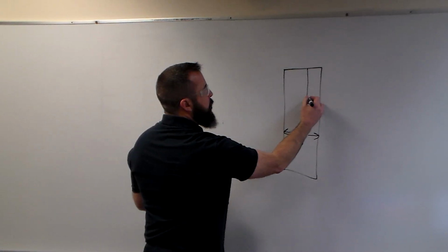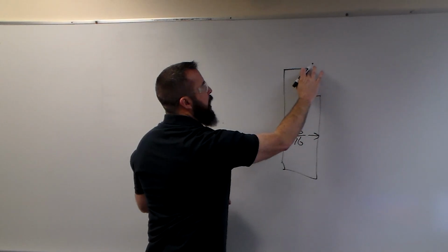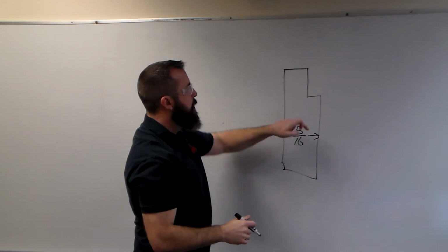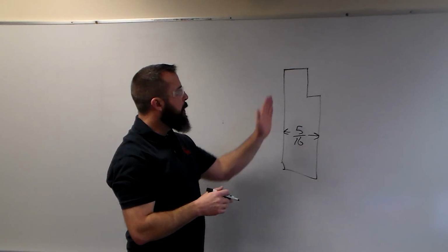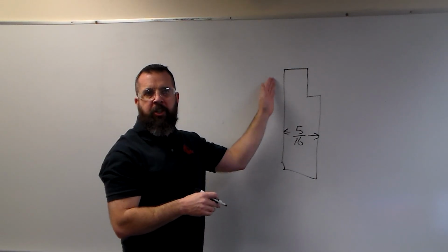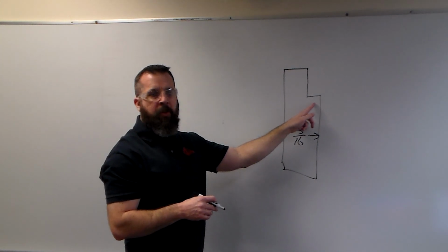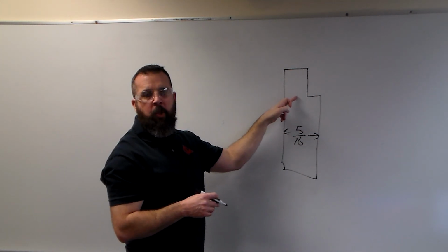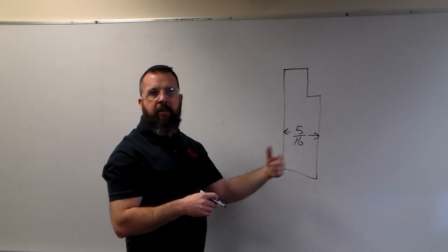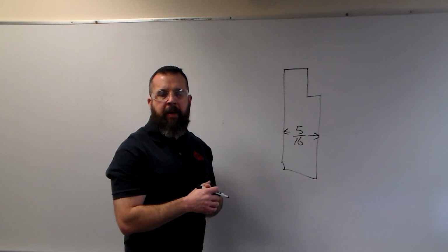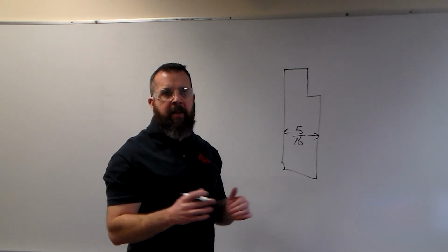But out at the grinder, you will be removing the material off the right side of the tool blank, and that's because our shoulders are on the left on this project, so we want to have one side of your tool be completely straight, and then the other side where there's not going to be any shoulders, that'll be where we have a shoulder step. You need to grind back down the tool, I would say about 5/16 or maybe 3/8 of an inch would be plenty adequate. Don't try to grind all the way down the tool, let's say 1 inch. You're just wasting your time and there's no benefit.